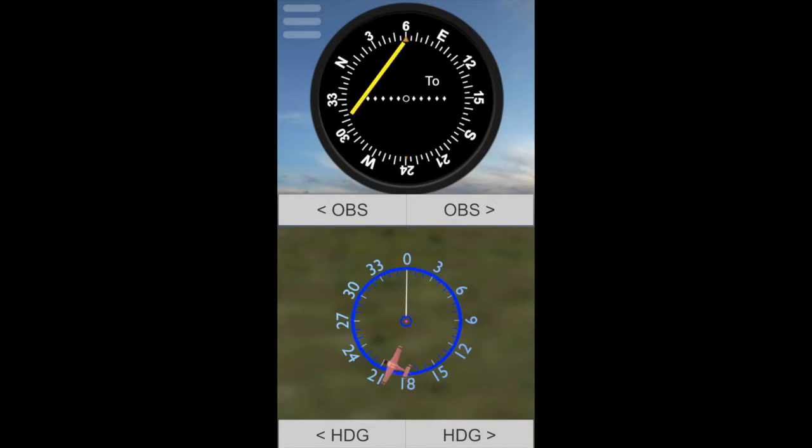What matters with the aircraft, if it's like a little circle or a dot or a point, is where it is with respect to the selected radial. Select a 060. All this is a to. Come to this side now, it's a from. Again, I'm focusing only now on the from, the to indications that you get in the cockpit so you can understand the concept thoroughly. Now let's pick another one.